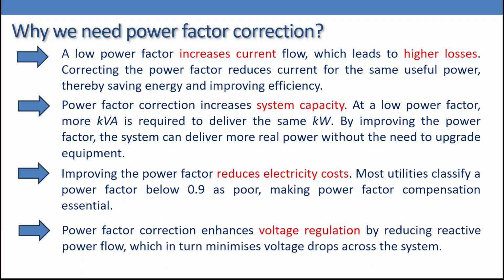Last point: the power factor correction enhances voltage regulation. So what do you mean by voltage regulation? For example, if you have a synchronous machine generating voltage, the percentage of voltage regulation will be no load voltage minus full load voltage over V no load.